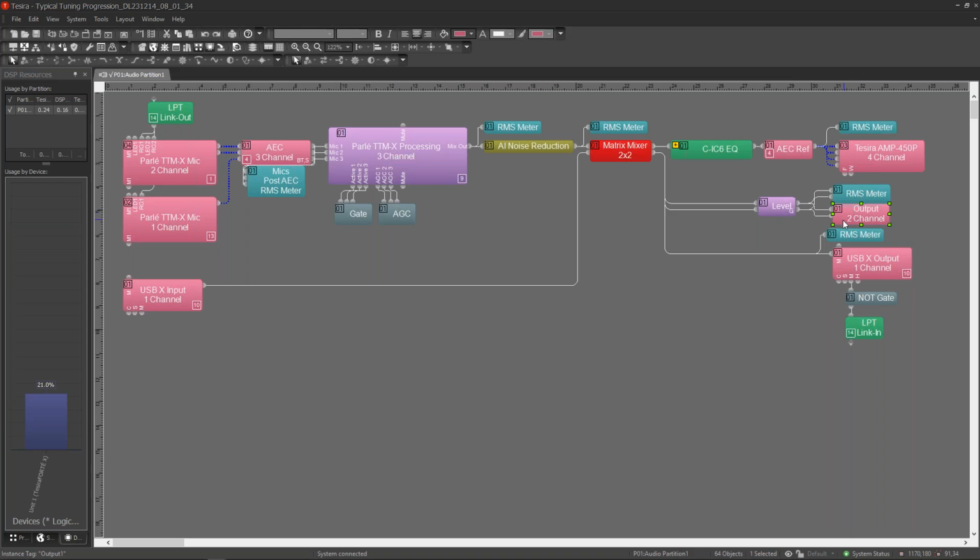If you can't do it, it's actually not the end of the world, because let's say in this system we're connecting it to a MTR or a Zoom room system. Whatever that downstream system is doing, so how the codec performs, any additional processing with AGC and noise reduction it has, we need to take into consideration anyway. So the next step after that is to actually get yourself in a test call.